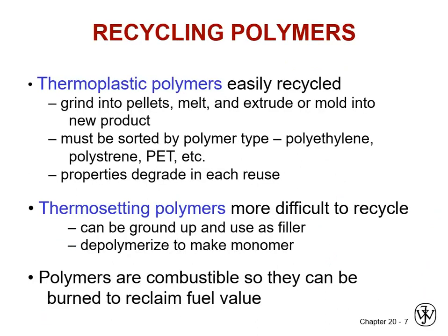Recycling polymers. This is where you do have a lot of choices, and this is where thermoplastics, even though they are definitely limited and their thermomechanical properties certainly have an advantage. They are easily recycled or downcycled because they can be remelted and run back through the extruder. Again, be careful about your reduction in molecular weight. There's still sorting required unless you're going for a general polyolefin blend, for instance, then there's less.